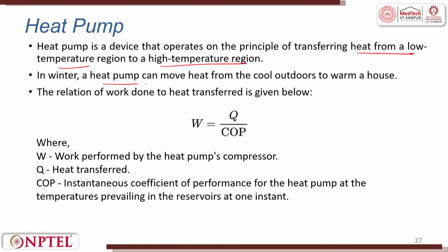In winter, a heat pump can move heat from the cool outdoors to warm a house. So work has to be done on it. Some mechanical energy is to be put in so that heat transfers from the lower temperature region to a high temperature region. The relation of work done to heat transferred is given below. Work is equal to Q by COP.